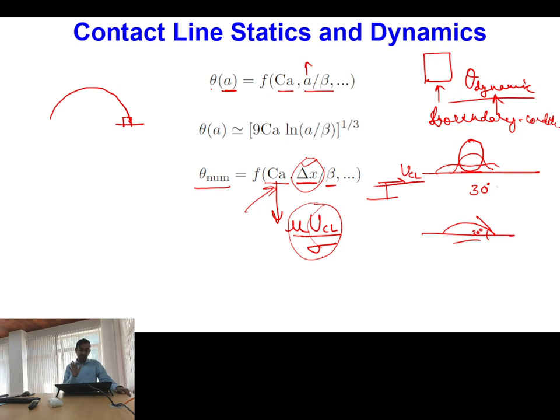Some people have done this type of formulation, and some people don't consider this cell size as the approach, they try to use a grid size of the order of the slip length scale. If you are using a grid size of the order of the slip length scale, then the velocity at the centroid of the boundary cell can be considered to be your contact line velocity.